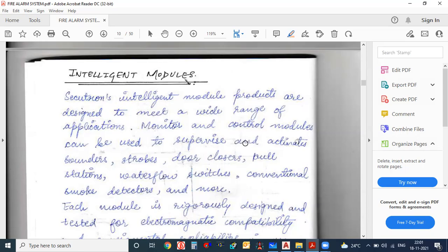It will be activated. Also, there is input module. For example, FM200, if it is released, it will tell the fire alarm panel through the monitor module. It will give dry VFC, voltage free contact. Okay. And the zone control valve for the firefighting. We have seen this the past week. Zone control valve, and there is a float switch.